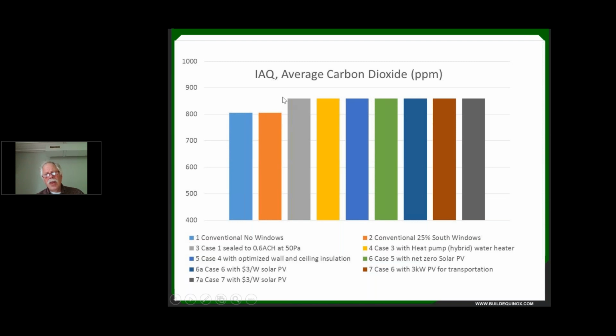Now, with smart ventilation that's actively sensing and bringing fresh air in as needed, as we modeled in ZEROs with the smart ventilator, and we had it set for 900 parts per million, I think, that dropped us to something less than that, about 850 parts per million. The reason it's somewhat less is that ZEROs also looks at whether or not, relative to the smart ventilator, the outside is nicer than inside. So for some months of the year, like in the spring and fall, it will bring in a bit of excess air just because it knows that's better air to condition than the air inside the house. And so it doesn't just maintain it right at whatever set point you put in. It depends on the climate and whether it's beneficial or not to bring in some excess air.